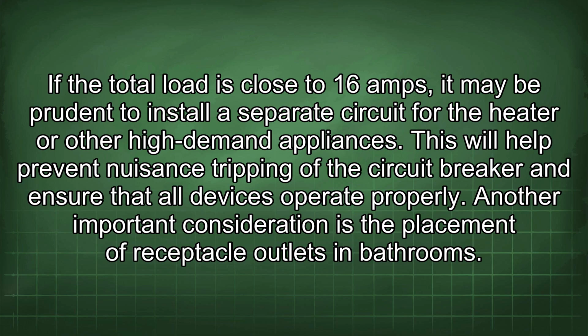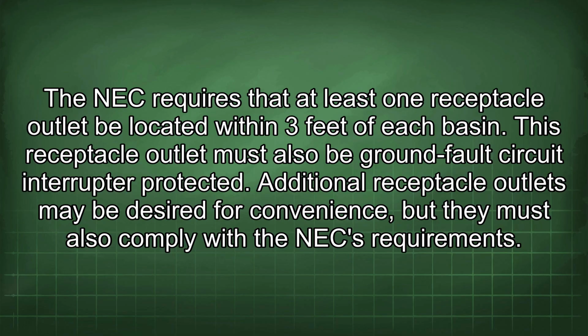If the total load is close to 16 amps, it may be prudent to install a separate circuit for the heater or other high-demand appliances. This will help prevent nuisance tripping of the circuit breaker and ensure that all devices operate properly. Another important consideration is the placement of receptacle outlets in bathrooms. The NEC requires that at least one receptacle outlet be located within 3 feet of each basin. This receptacle outlet must also be ground fault circuit interrupter protected. Additional receptacle outlets may be desired for convenience, but they must also comply with the NEC requirements.